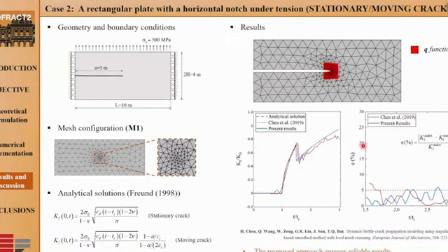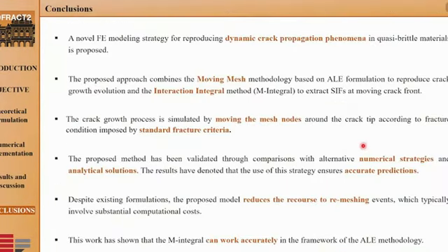So in conclusion, we present a novel finite element modeling strategy for reproducing dynamic crack propagation phenomena in quasi-brittle materials. The proposed approach combines moving mesh methodology and the interaction integral. So the proposed model reduces the recourse to the remesh events, which typically involve substantial computational cost, and ensures accurate prediction. Finally, this work has shown that the interaction integral can work accurately in the framework of the ALE methodology.